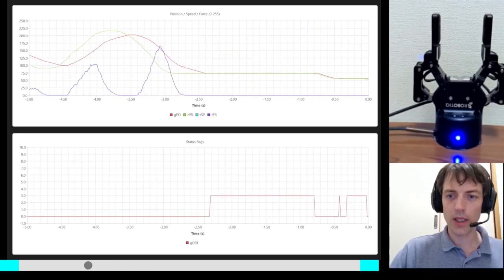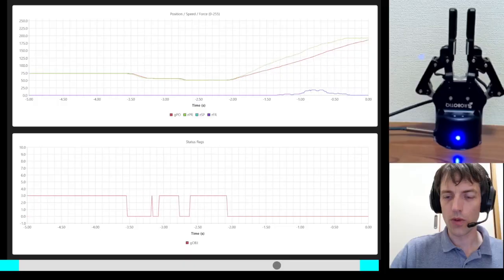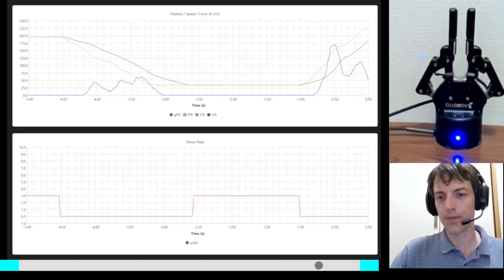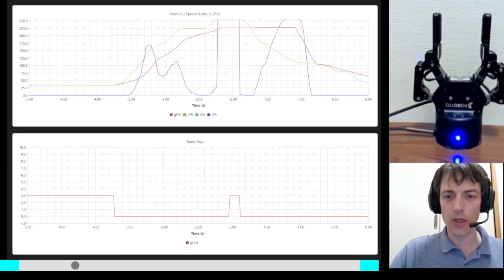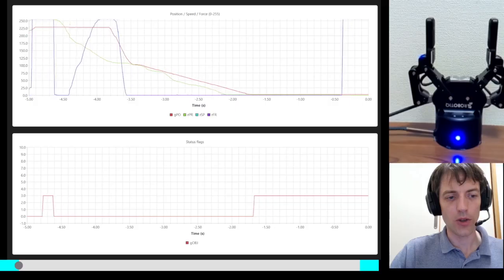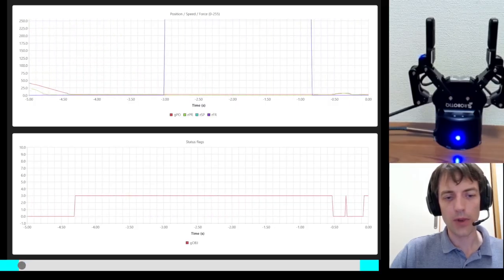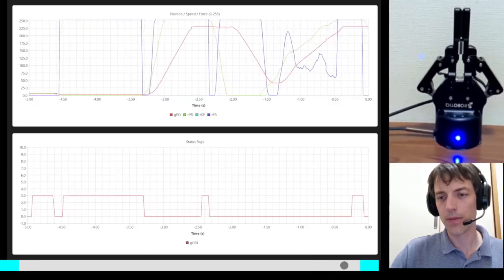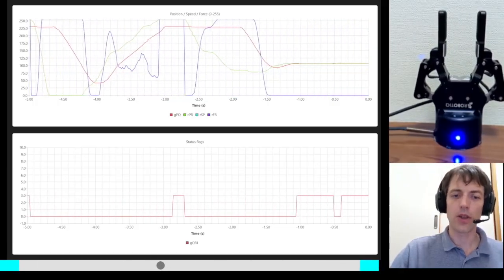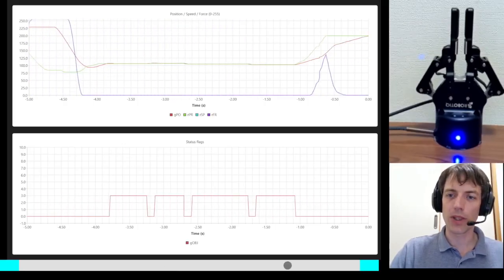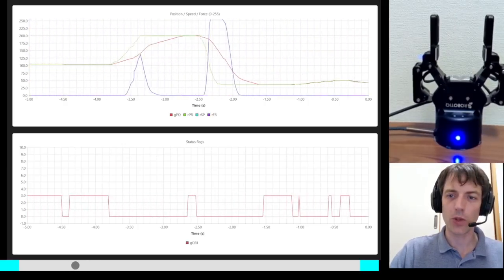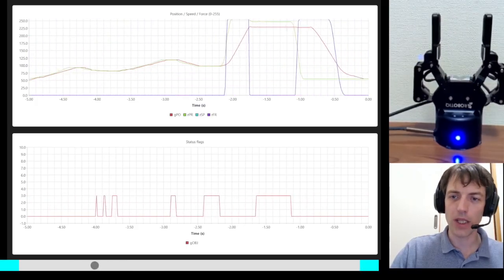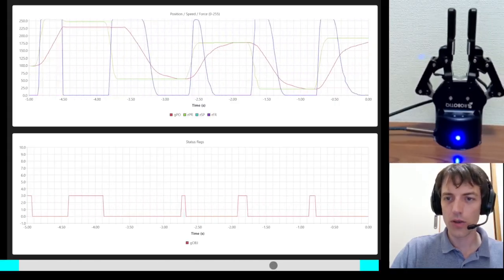At the bottom, you can see the current position of the joystick in its control range, and there is the control buffer that we saw previously. Now I'm controlling the gripper position with the mouse of the PC. If I make small motions, the gripper will move slowly. If I make large motions, the gripper will go fast.